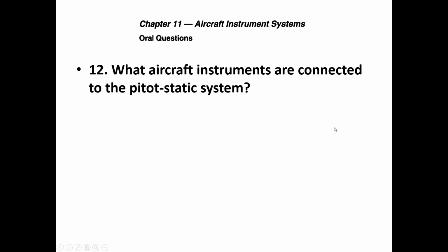An oral question, you're not going to have much problem with the oral questions, because if there is a distinguishing factor, you can explain it since you're actually verbally answering the question. Your DME might ask, what aircraft instruments are connected to the pitot system? Well, at this point, I think it's definitely fresh in your mind. The airspeed indicator, the VSI, vertical speed indicator, which could also be referred to as rate of climb, and the altimeter. Let's see what they answer.